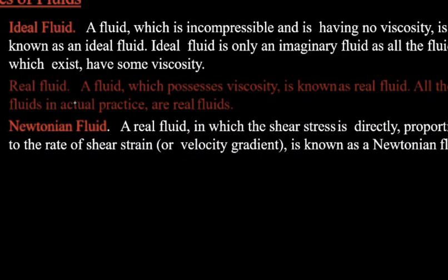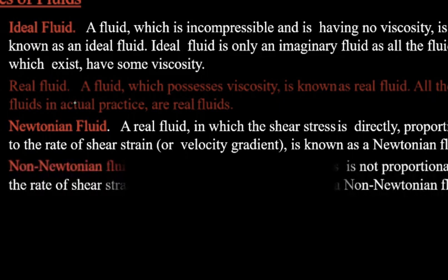Next we will come to the Newtonian fluid. So we already know what is Newtonian fluid. A real fluid in which the shear stress is directly proportional to the rate of shear strain, that is tau is proportional to du by dy, is known as Newtonian fluid.